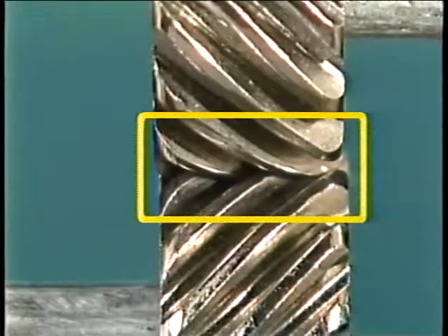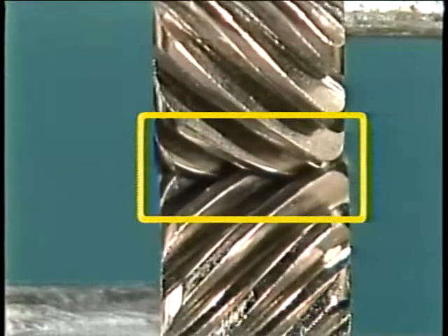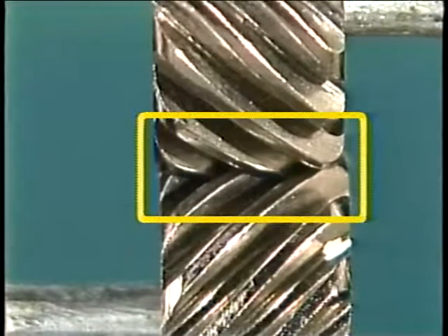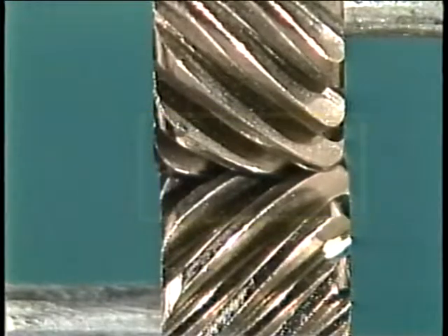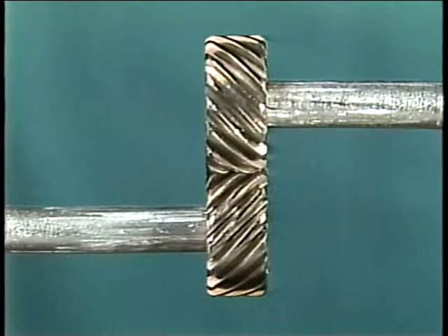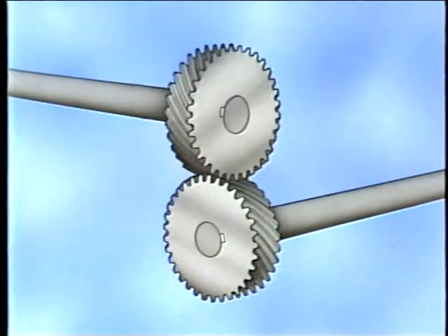If the face of a helical gear is wide enough, several teeth will be engaged at the same time. This multiple engagement of gear teeth allows a helical gear to carry a larger load across a single gear set. Helical gears are normally used to transmit power from one parallel shaft to another. However, two helical gears may also be crossed to transmit power at 90 degrees. Helical gears are generally preferred over spur gears for high-speed operations because they can handle greater loads and they run smoother and quieter.